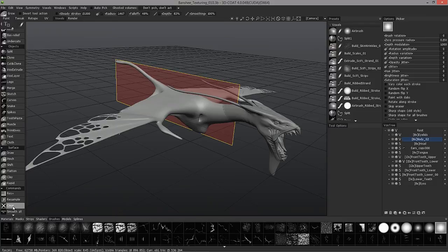Okay, and clear will simply clear just the object from the layer. Now this is very handy if you want to start over. For example, maybe you merged a model in and it just didn't come in with enough resolution initially. You want to start over. You don't need to retype the name of your layer. You don't need to go back and have to increase the resolution amount on that layer and all that. You can leave it as it is, just clear the object itself, and then restart, maybe merge the model in again and hit apply and so on.